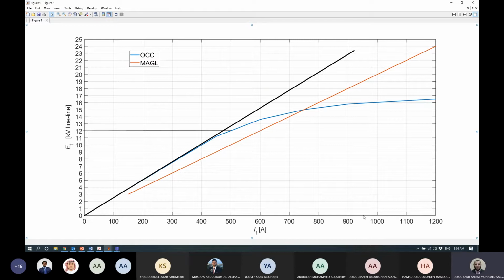After drawing the short circuit current, we draw another curve like that, and you should make another scale for the current. You will find that at the same value of field current, which was 750, you get this value of armature current, which is already given as 7 kiloampere. So this is now representing the armature current drawn from the supply.